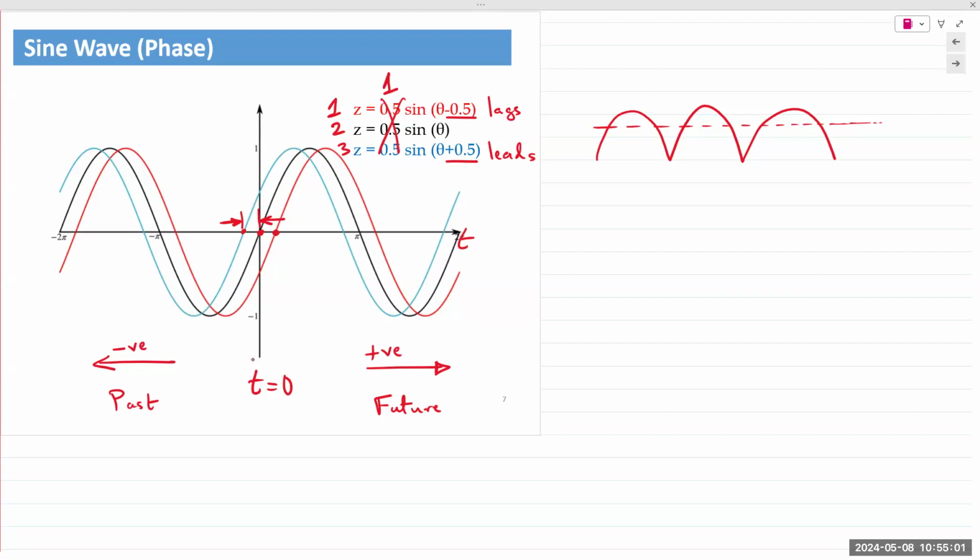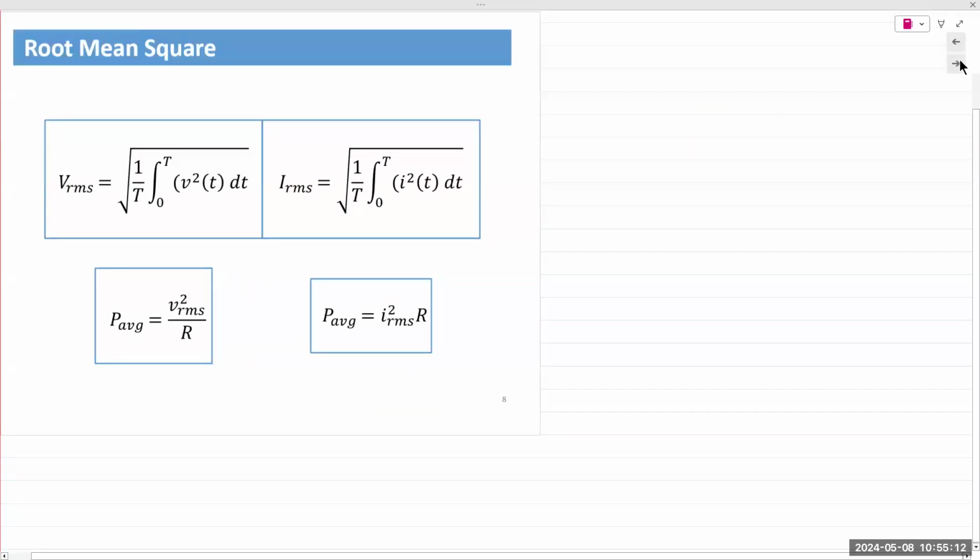And because we squared the waveform at the beginning, at the end we will now do a square root. So they came up with a new term called root mean square. It literally is the square root of the average of the square of the waveform. Mean, of course, is another term for average. So again, this describes the average DC value of that waveform, and it's popularly known by its acronym, RMS. It literally is the square root of the mean of the square of the waveform.